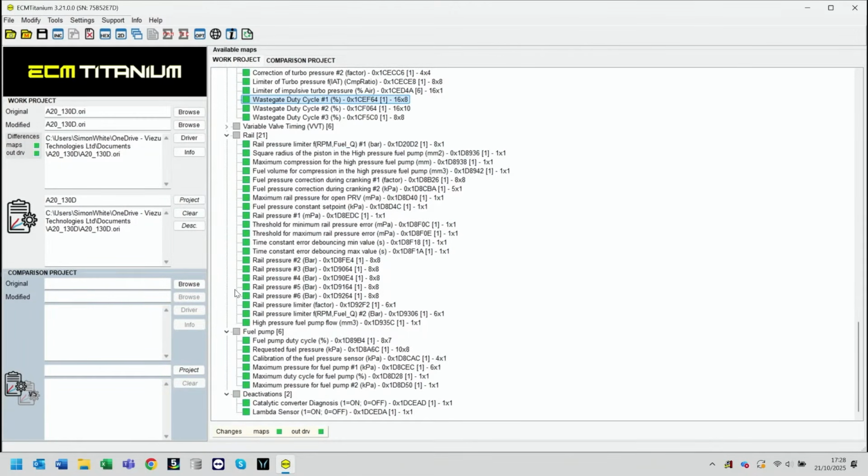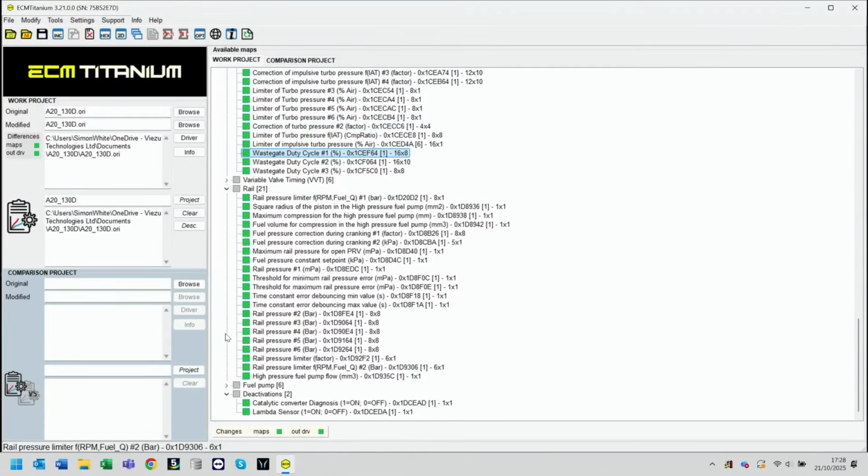that folder. We will make some changes to our rail pressure to help support those modifications we're making elsewhere in the ECU. But in things like our fuel pump, or standard fuel pump, we're not modifying that, so we don't need to change it. And on a stage 1, and this is one of the things about ECM as well, we actually have support for our stage 2 in here for high flow exhaust systems, for off-road and motorsport use, for high flow performance or even motorsport catalytic converters.